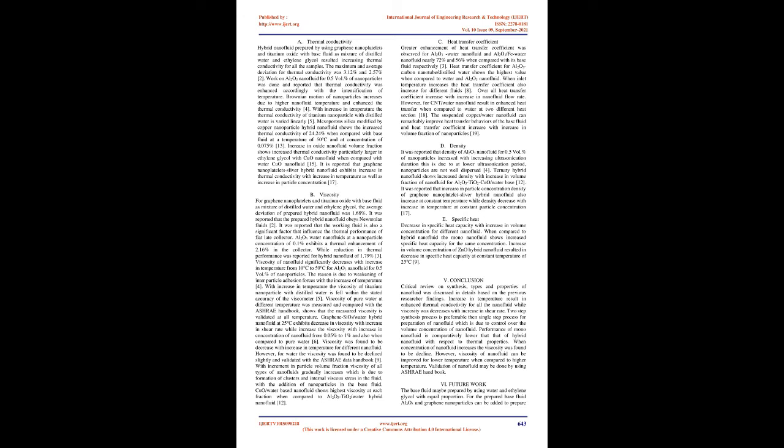It was reported that the working fluid is also a significant factor that influences the thermal performance of a flat plate collector. Al2O3-water nanofluid at a nanoparticle concentration of 0.1% exhibits a thermal enhancement of 2.16% in the collector, while a reduction in thermal performance of 1.79% was reported for hybrid nanofluid.